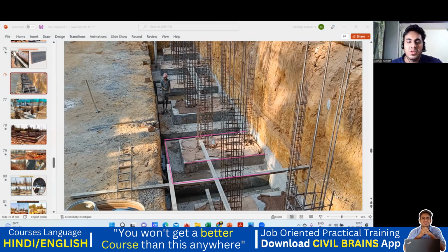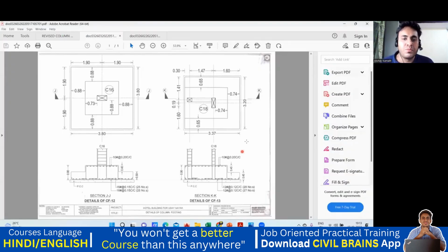Similarly on the top also the same thing. This length, this breadth, and this length, you add all 3. Here there won't be any shuttering because it is attached to the wall. That portion of shuttering you have to take out. I'll do one for you. This only we'll try to do. Quickly, I'll not do it in Excel. Here itself, I'll do that.